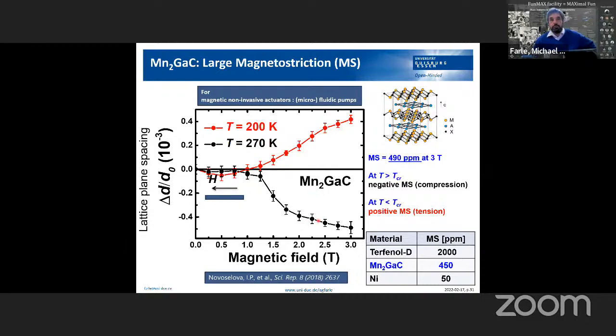So as a function of temperature, the magnetostrictive constant changes, and I say dramatically, because now we are on the order of 4 times 10 to the minus 4 in magnetostriction. So this is 5 times smaller than Terfenol, which is known to have the largest magnetostriction.